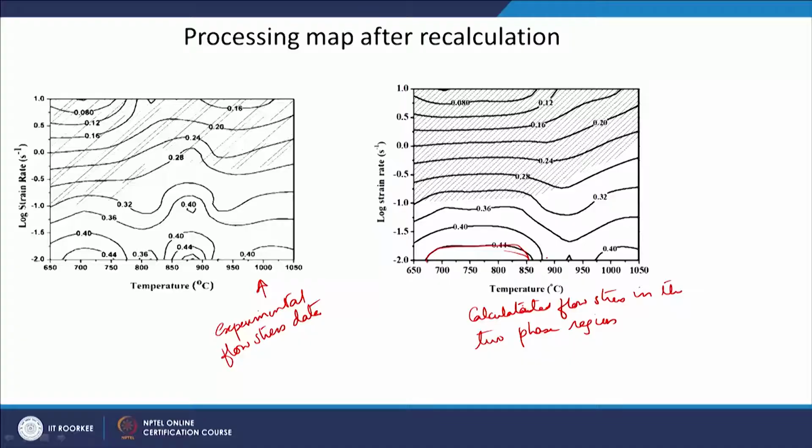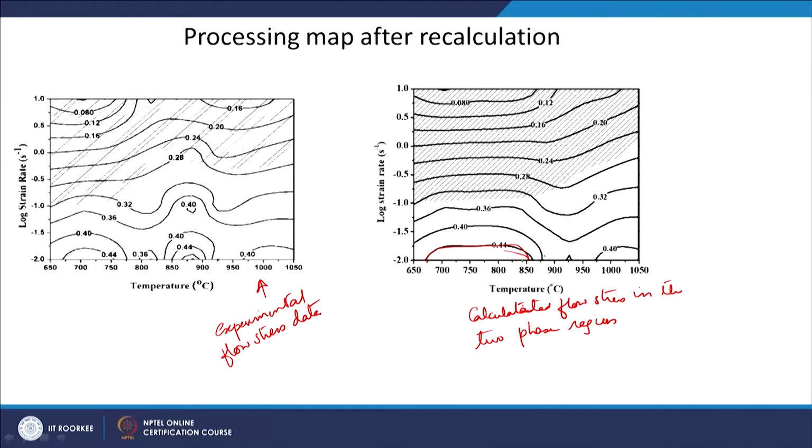recrystallization. And in fact, at higher temperatures in the microstructure also, there were elongated grains and only a few grains were showing the recrystallized behavior. So, you are able to see that at those locations I am not seeing high efficiency. Of course, in the beta phase field the high efficiency is the same as what you get here, because this is for a single phase. So, the main thing here is that we are able to get a high efficiency region for all the temperatures where we were able to see recovery and recrystallization. So, this is one